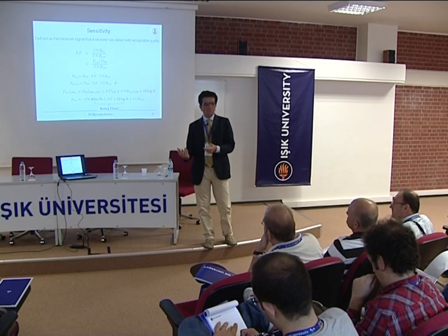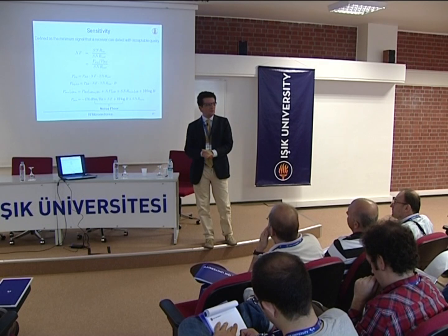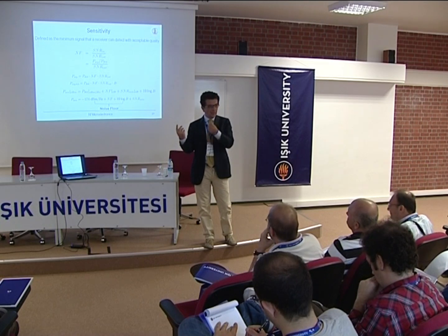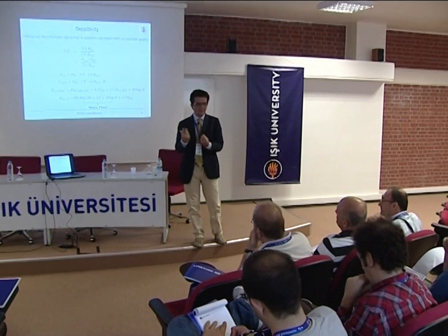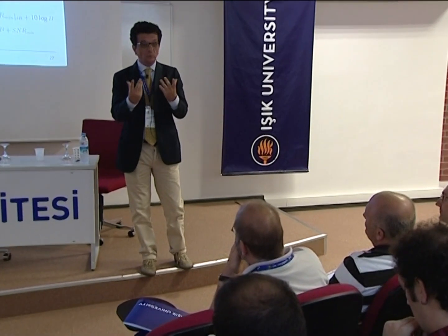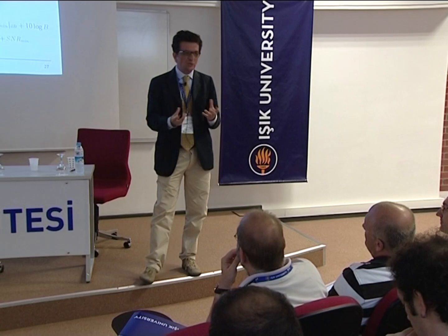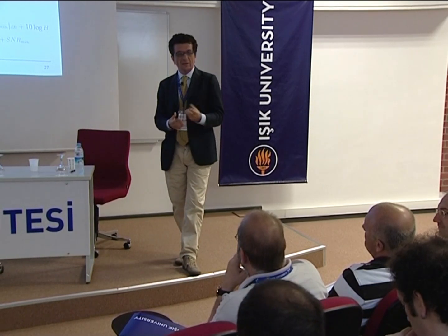We made some work on that, but then we discovered that at the very end, when you try to go to the minimum, the minimum noise is given by the ratio between the voltage series source of a device over the current, the parallel current. That's the optimum noise resistance. It's not much different from the resistance you at the very end have in the antenna that is receiving.